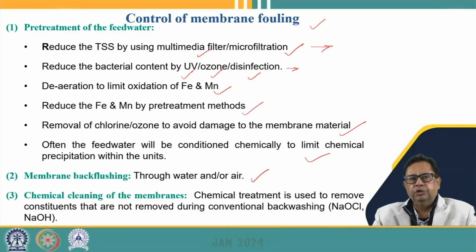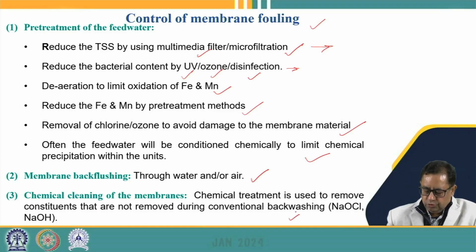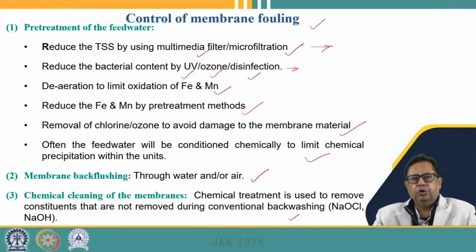We can remove the pores which are blocked, or we can reduce the membrane pore narrowing that is taking place. This can be removed by back flushing or backwashing the membrane regularly using water or air. Similarly, we can also go for chemical processes for cleaning the membranes.